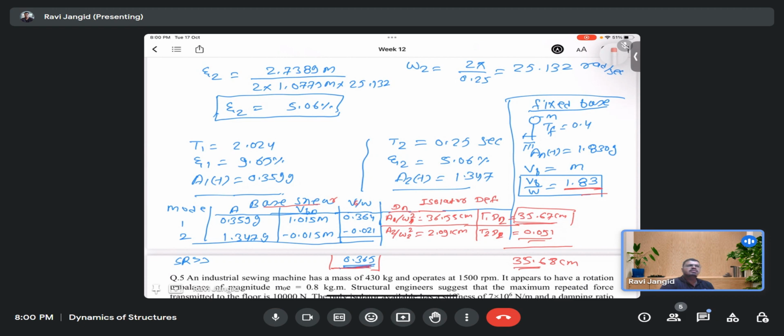And there was one more doubt you were asking about, the setup you have. For that, you can attach your sensor or accelerometer at any of the floors if you want to find out the modal frequencies. Let us suppose your model is three-story, so you will have three modal frequencies. You can put the sensor at any floor, and you will get resonance in each of the three modes, so you will easily get your modal frequencies.